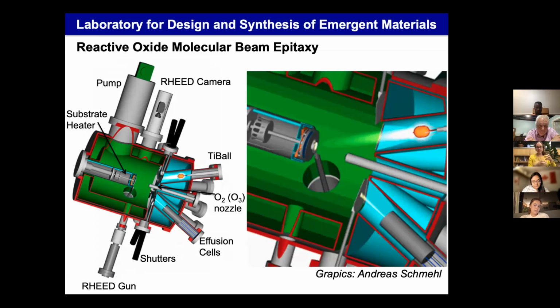Then we heat them up so that we have thermal evaporation. These atoms, we're just thermally evaporating them, just like a puddle evaporates. But the precise thing about MBE is that we can do this with incredible long-term stability and controlled flux of the atoms.